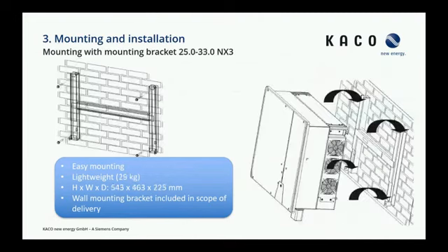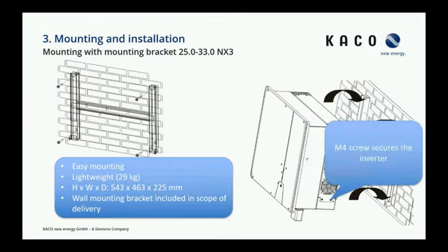This is the picture for the biggest NX3 inverters up to 33 kilowatts. We can see the bracket is here really big, but again, we just have to mount the bracket, and after that we can hang up the inverter and secure the inverter with the M4 screws.